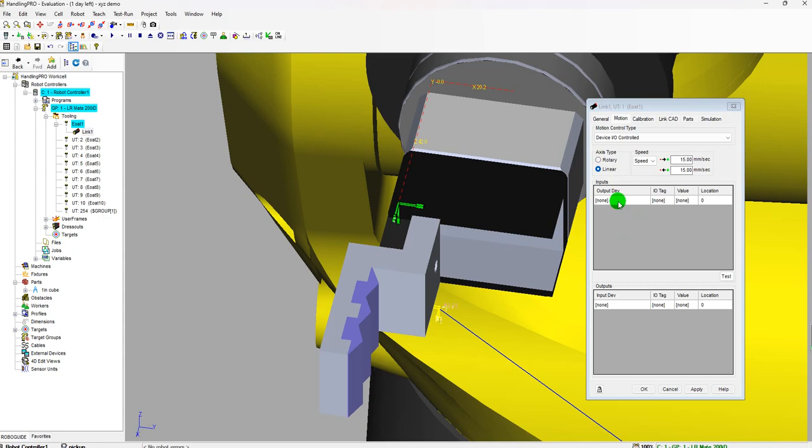Let's first set up the control. As I mentioned in class, the input here is based on the drawer's perspective, so it's an input for the drawer. But when you select the controller and assign the IO, you see it's the output. Why? It's the output from the robot. For the drawer, it's input. For the robot, it's output being connected with this drawer. So that's why.